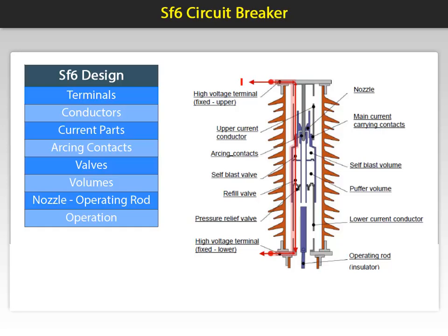The risk for gas leakage is also problematic. Proponents of gas technology, however, tout much less chop occurs during the interruption process. Engineers must take these trade-offs into consideration when designing medium-voltage switchgear.